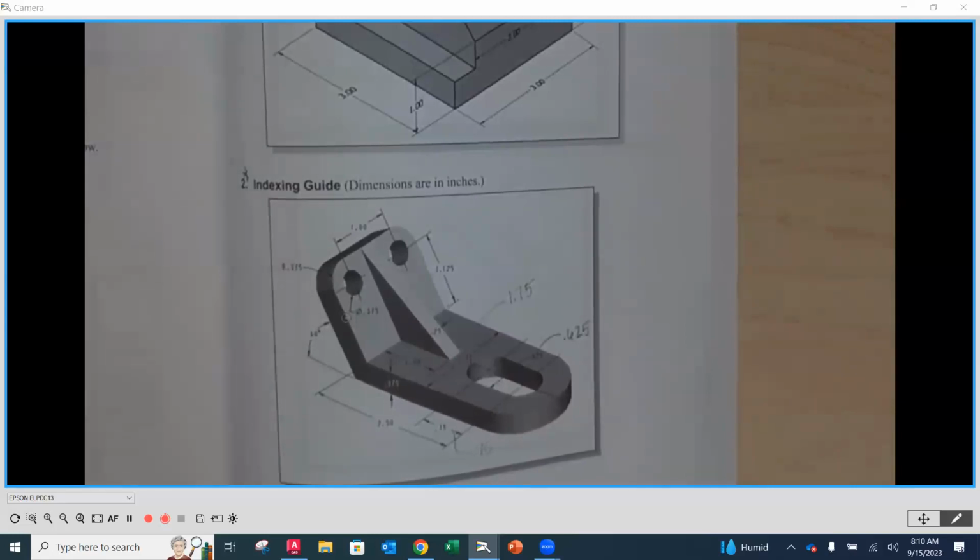Okay, now we haven't gotten to dimensioning yet, but I've been telling you, you have to dimension in the view where we see it as its true size and shape. So we need to see the view where we see those holes as circles. Okay. Additionally, the radius that we see here as well. Okay. So we need to create an auxiliary view looking straight on to that surface.